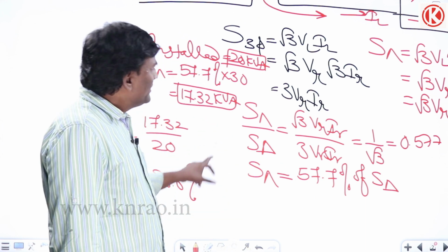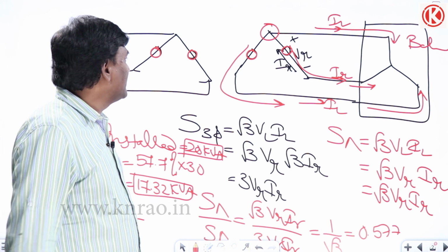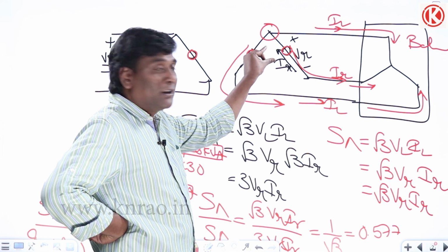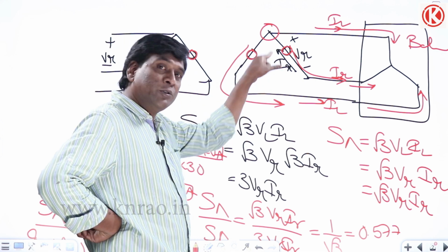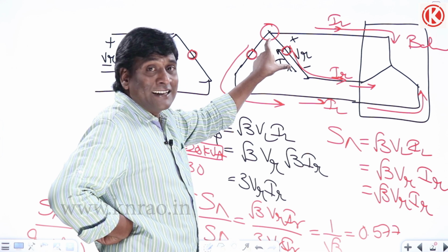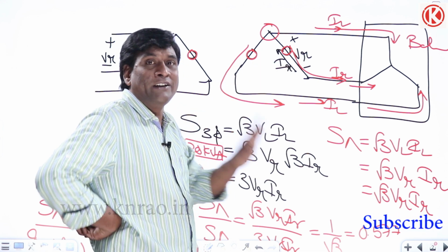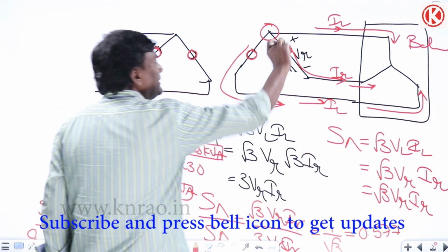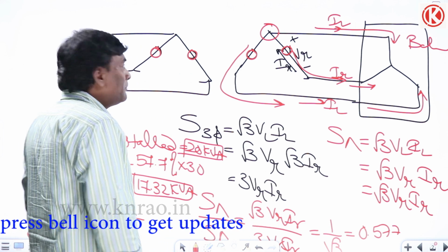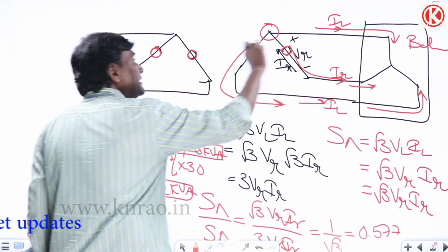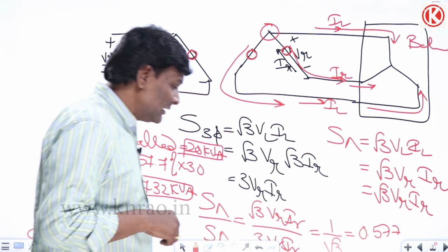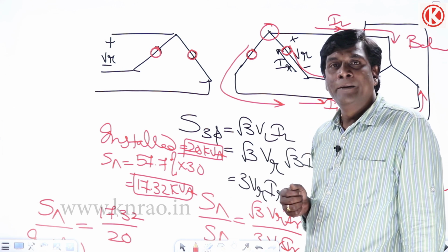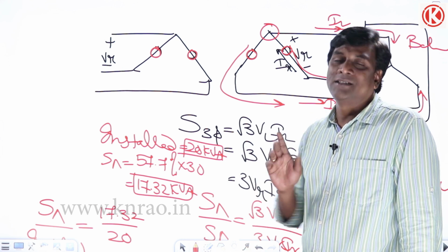Anyway, the point here is, if we go ahead with intricate analysis, if I have this closed delta with rated voltage, rated current, and if I open circuit it, also rated voltage, rated current, in the sense each transformer phase is supplying 10 kVA. So with closed delta, 10, 10, 10, total capacity is 30. But now in open delta, 10, 10, 20, installed capacity is 20 kVA, but you can get a maximum of 17.32 kVA only. Meaning that your investment is going to be wasted.